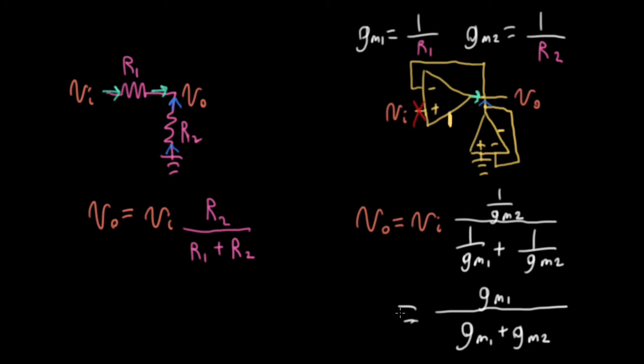So what that means is that in addition to being a voltage divider, if you want to use this that way, i.e. if you're setting the bias current here to something that's not 0, it's also a buffer. So the input here is buffered from whatever is out on the other side. And that's the case if you have a BJT-based OTA, but those do have non-perfect input impedances. But MOSFETs have extremely high input impedances. So this is a very, very good buffer.